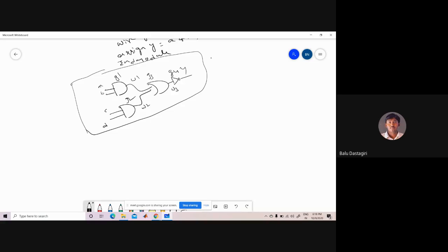So this has to be represented in the form of wires. When you are writing the program here, the first thing is module AOI gate. The output is Y and the inputs are A, B, C, D. Next, specify the inputs and outputs here. Input A, comma B, comma C, comma D, and the output is taken as output Y.